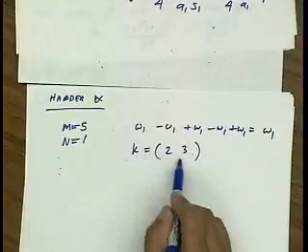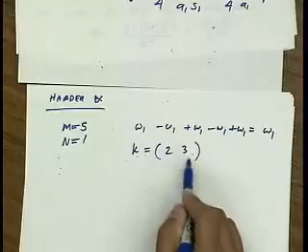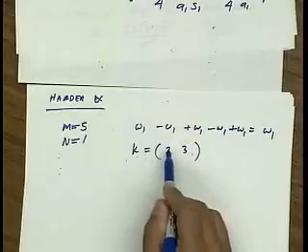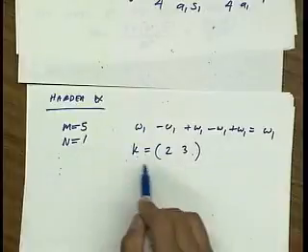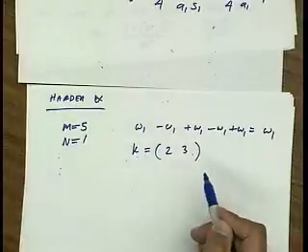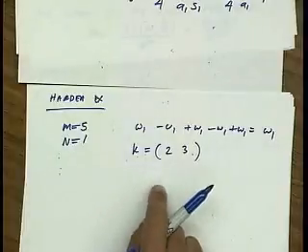So remember, 3 plus 2 is 5. It's a fifth order nonlinearity. And as long as I get 3 omega 1s and 2 minus omega 1s, I get a tone at omega 1. You can, of course, do the complex conjugate, 3, 2, get the same answer, right? Everybody see where this comes from?